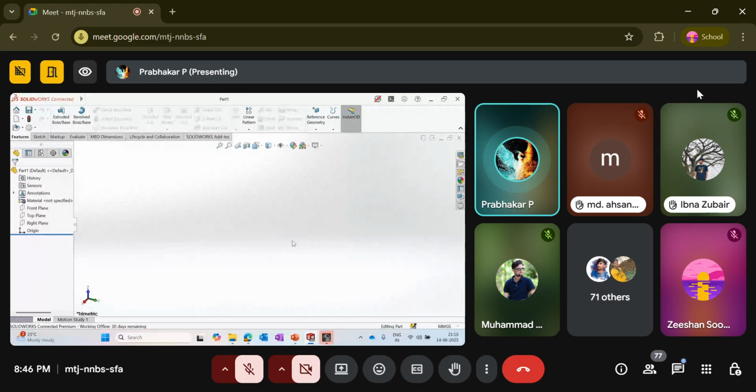So the three major things included in SolidWorks are feature-based, parametric, and associative properties. In most CAD tools, not only SolidWorks, all these three features are included, unless it's a 2D modeling tool, which won't link to the assembly. In AutoCAD, if you create a 2D drawing and then create an assembly drawing, and you edit something at the part level, you have to edit the changes in the assembly also.